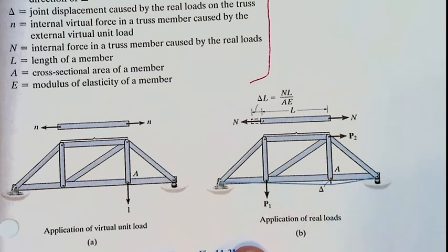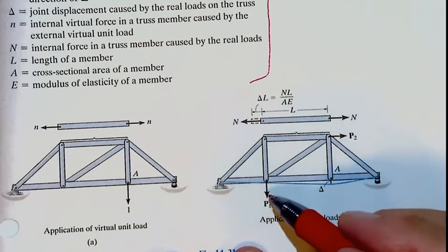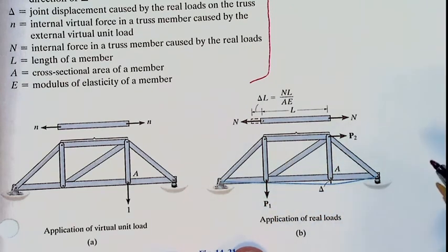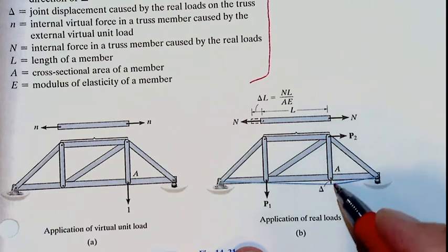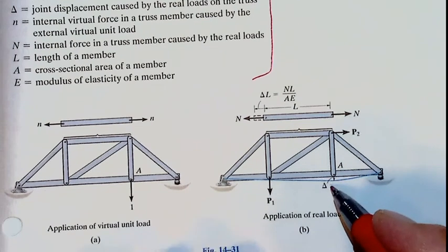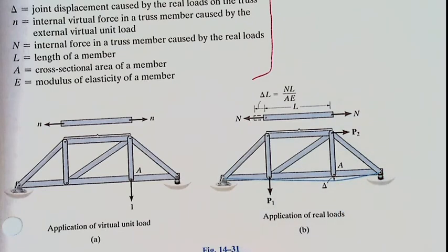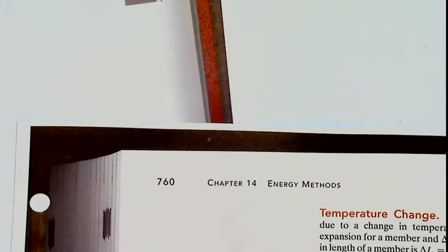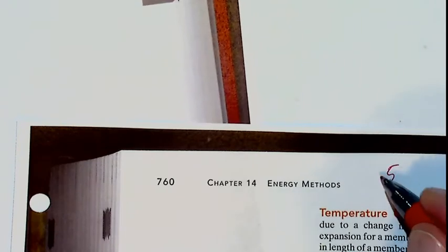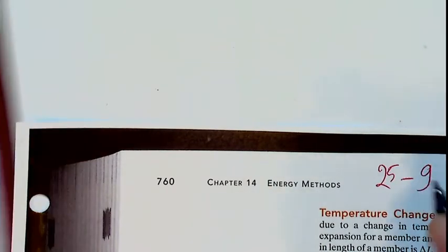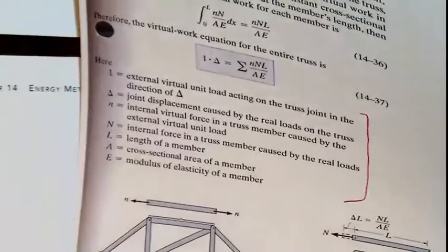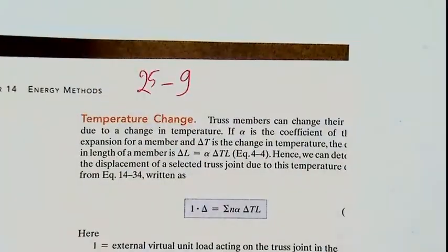If I want to find displacement here, I don't need to use the method of virtual displacements, but I want to find it here. Then we will apply here a unit imaginary force, or virtual force. So then the displacement I want is here.